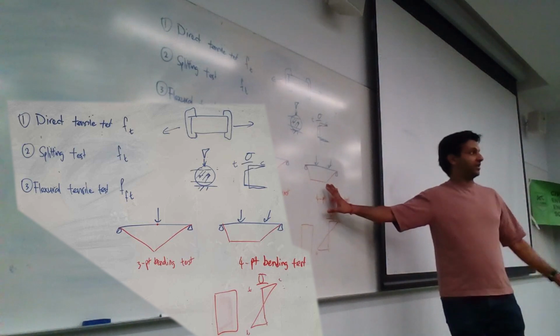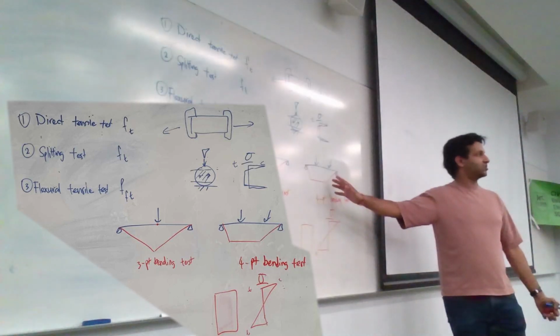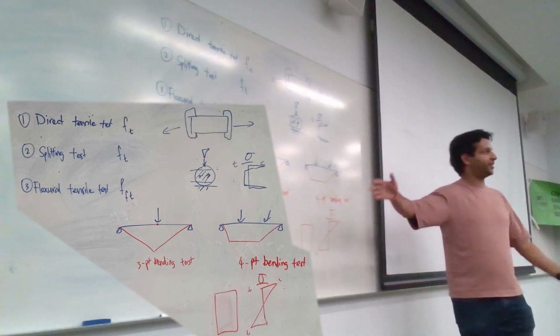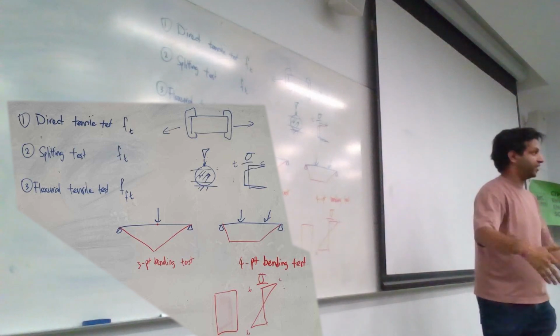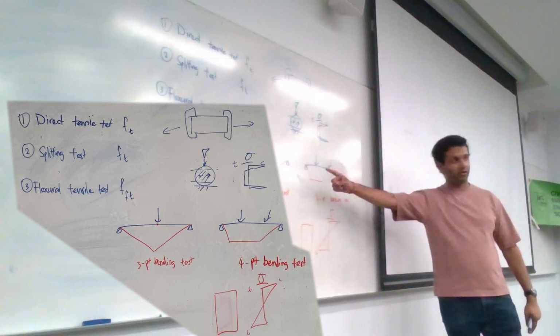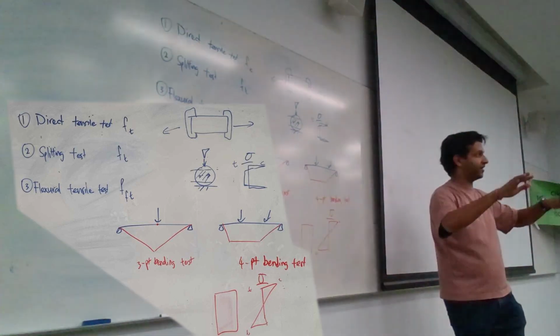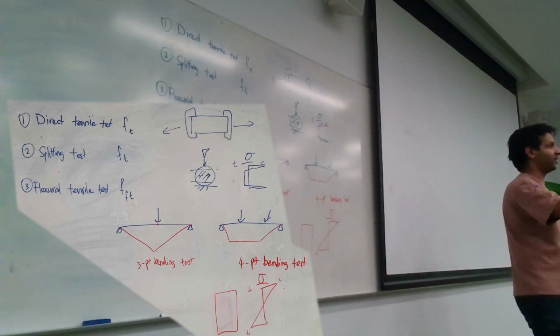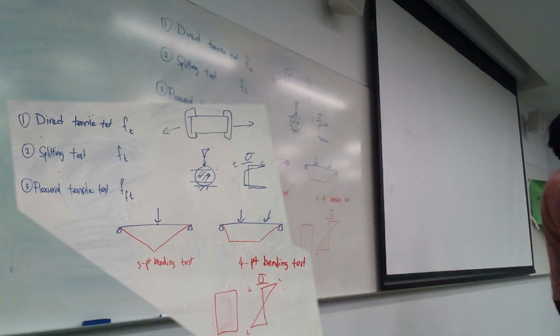Test methods, by the way, are standardized. At this stage, there are standards out there under the Australian standards that literally tell you if you're going to do a bending test, this is how long it needs to be, this is where your load needs to be, and then based on that you calculate it, and everyone will just believe you.